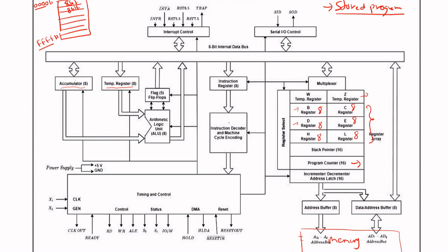Then these two values go to the arithmetic and logical unit, and then basically the data manipulation operation happens here. Now, the instant the data manipulation operation execution is done, the flags are updated. We have 5 flags basically. So these 5 flags will be updated, and then they will also be accessible again to be used in further operations here.